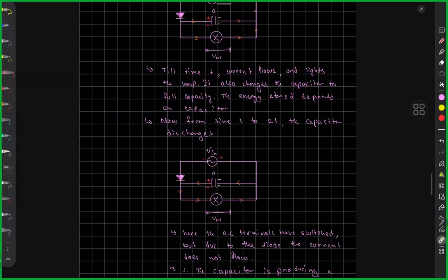And then for the next half, what happens when there is no voltage supply? And by the way, why is there no voltage supply? Because, let's say, conventional current in this route just cannot reach the negative terminal, can it? The diode stops it, right? So if you have half the cycle due to this, the next half cycle is blank. Why? Again, the diode stops the current. Makes sense?